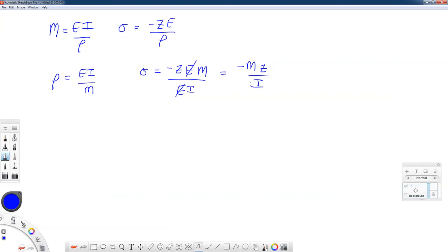The last thing that we want to do is take a look at deflections. And from taking a look at our deformed beam, now we can relax the constant moment to a moment that changes with position x. So there can be various local radii of curvature. Let's say we were on this particular spot with some radius of curvature here, along a certain length of beam, we have a certain change in vertical displacement. This would be the distance dx, and the vertical displacement we're going to call w.